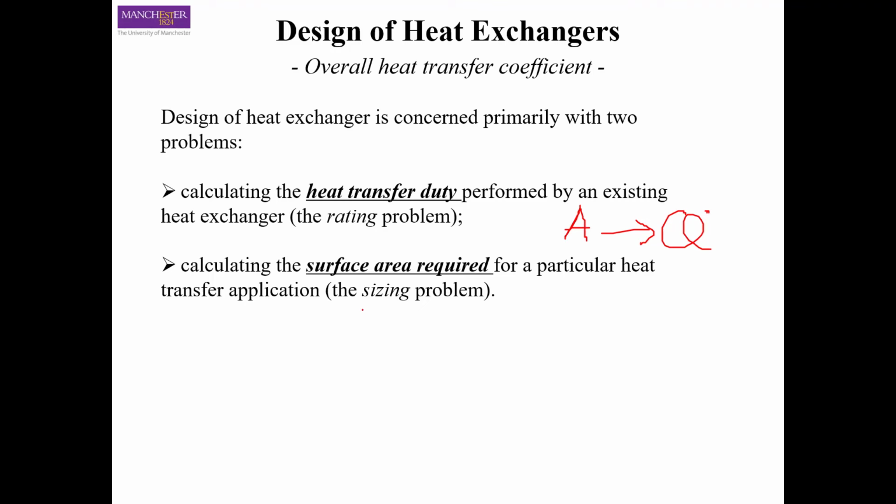And then we have another problem, which we call the sizing of the heat exchanger, and that is when you are designing a new heat exchanger. What you know is the heat duty, the amount of heat load that you have in the process, and you want to calculate how much area you need for that particular heat transfer. Because when you buy a heat exchanger you have to give them the area of heat transfer, and based on that the mechanical engineers, for example, design or build a heat exchanger for you.